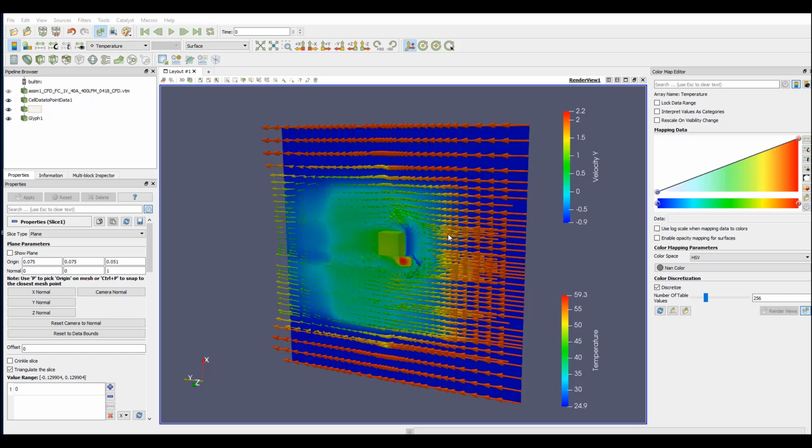So you can see all those flow patterns, rebounding flow and vortex flow, together with the temperature distribution and hotspot in the package. So all those natural convection and forced convection CFD results could be set up like we talked about before in the Celsius thermal solver. Okay, now this concludes all those example demonstrations.